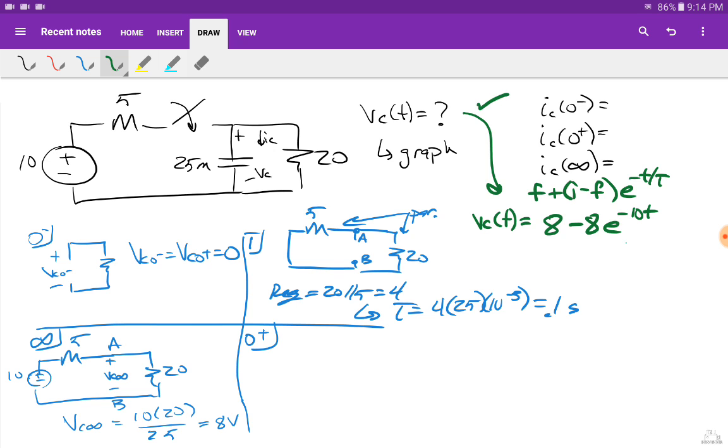All right. To graph it, it's going to start at 0. Voltage in this will be seconds. It's going to start at 0 and go to 8. So I'll just go up like that. But please do not forget, this has to stabilize. It stabilizes at a very specific point. It stabilizes always at 5 tau. 5 tau, in this case, is 5 times 0.1, or 0.5 seconds. Okay, so it goes to 8 after 0.5 seconds. Bam, the second part, the graph, has been done.